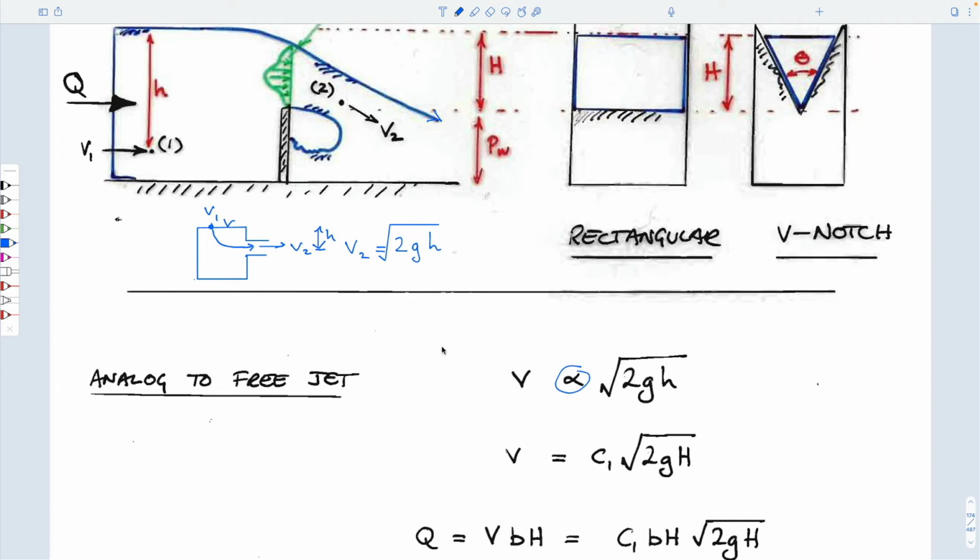If you see by the side of streams, I know there's a back road to the airport on Spring Creek. There's a little corrugated circular cylinder that's pushed into the stream. It comes out of that with a little box on top, and it's got a solar panel and a little telemetry aerial antenna on it, that's a stream gauge.